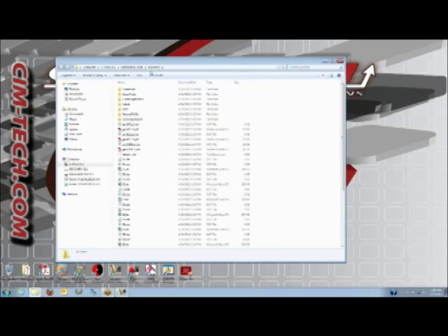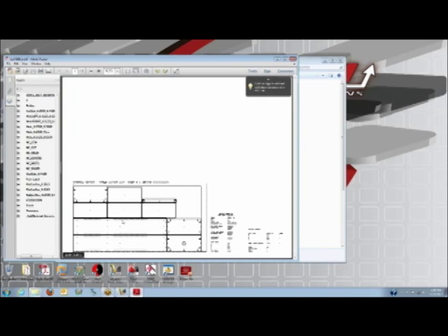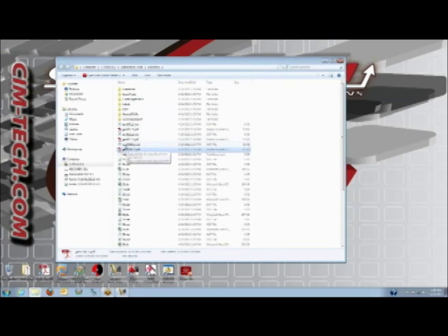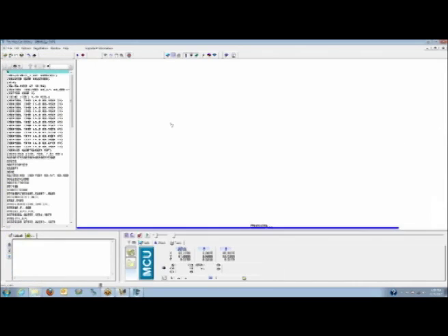I open my results and there are the results with the same name as the Inventor model. I've got my nested sheets available as PDF files so I can view my nests, and they can be sent to any printer. I've got the entire G-code file programs on here as well. You can double click on the G-code file and it shows in our toolpath verification program.